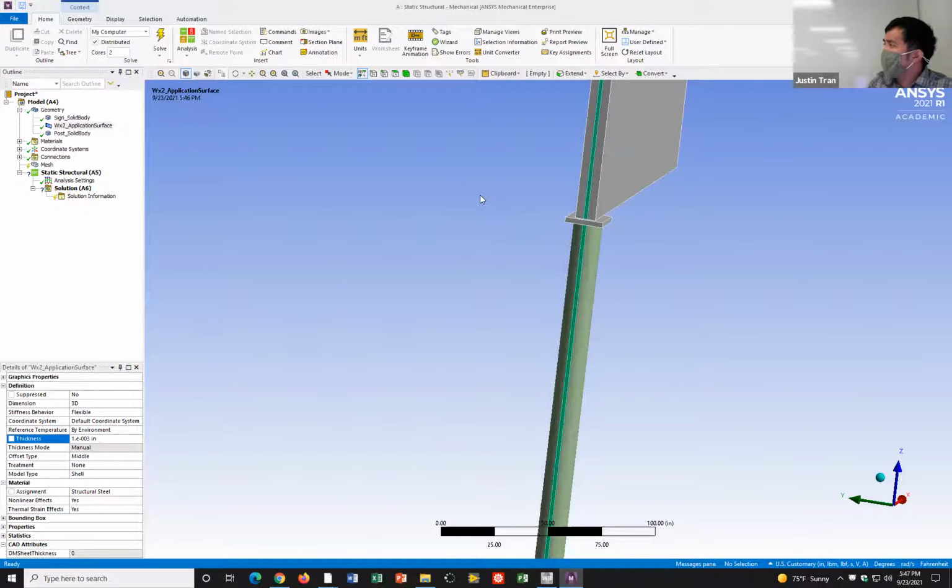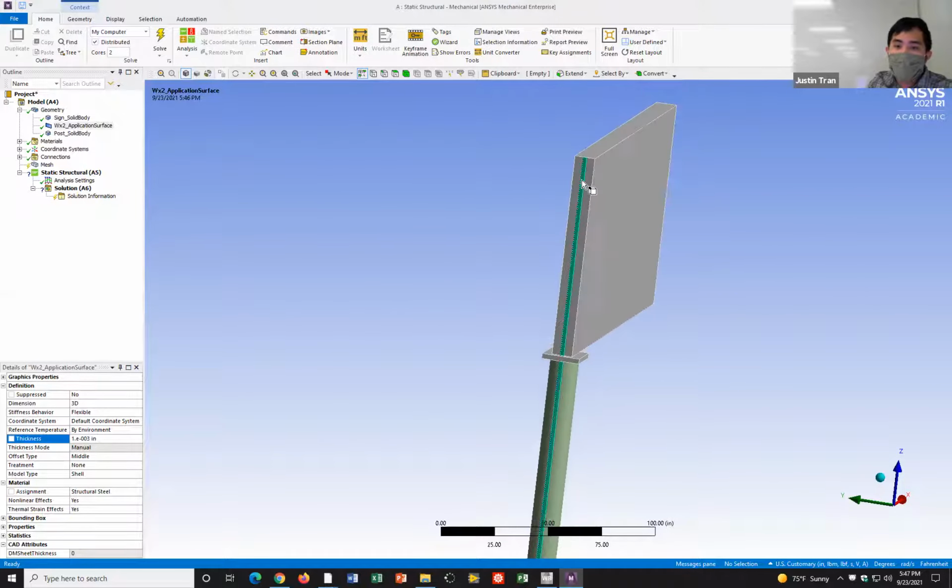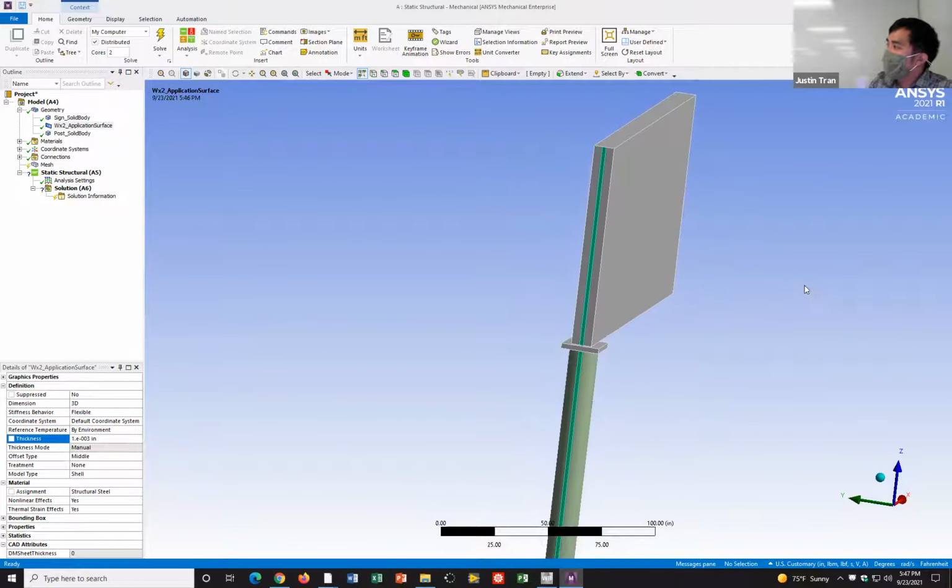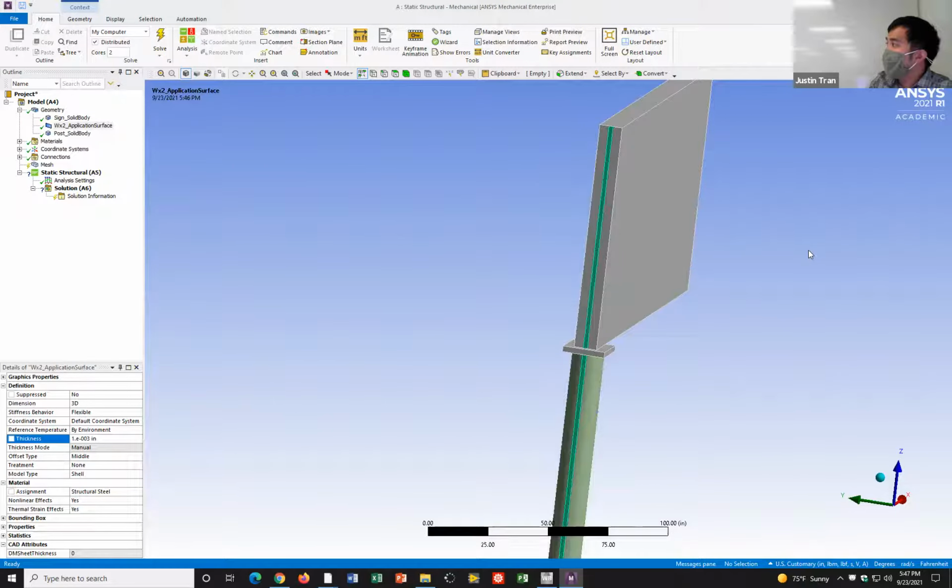And one of the appendix notes that I talked about, I think a week ago, actually gives a little tutorial on how to do something like this, because this is really useful to be able to create a surface to apply boundary conditions on. What's common, and a lot of people do this for their final projects, is they want to do some kind of simulation on a wheeled vehicle, so something like a skateboard or a car, right? In those situations, you would have your wheels contacting the ground below your vehicle, right? And in order to apply a boundary condition on just the parts where it contacts the ground, you need to create an extra surface like this in order to make that boundary condition, okay?